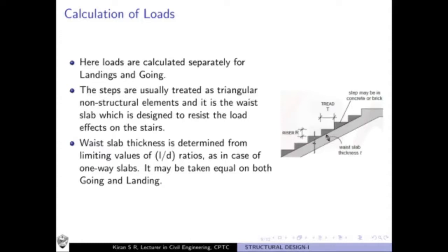They do not add to the strength of the staircase. And it is the waist slab which is designed to resist the load effects on the staircase. So whatever load comes over the staircase has to be resisted by this waist slab. Okay, so we are going to determine the thickness of the waist slab. We are going to design this waist slab and not the steps.